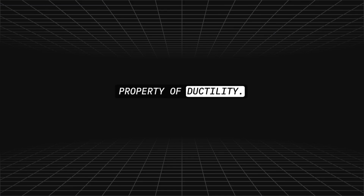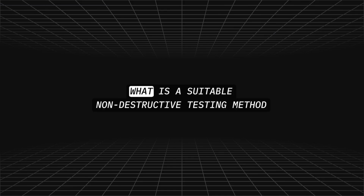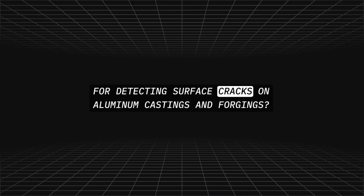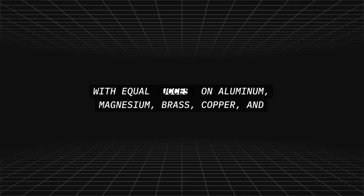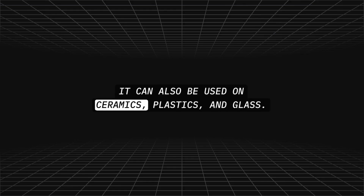The property of ductility. What is a suitable non-destructive testing method for detecting surface cracks on aluminum castings and forgings? The dye-penetrant inspection method detects surface cracks with equal success on aluminum, magnesium, brass, copper, and titanium. It can also be used on ceramics, plastics, and glass.